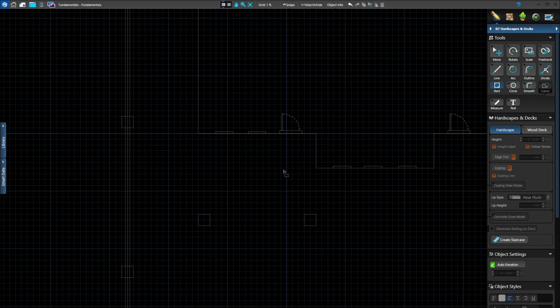We worked with the rectangle tool earlier when we wanted to draw those 2 foot by 2 foot columns. And we used the shift key to prompt the system to make squares, to make all 4 sides even. Here, we've got a 20 foot by 16 foot rectangle. So an actual rectangle, you don't have to click anything, just engage the tool and drag it or stretch it to the desired dimensions.